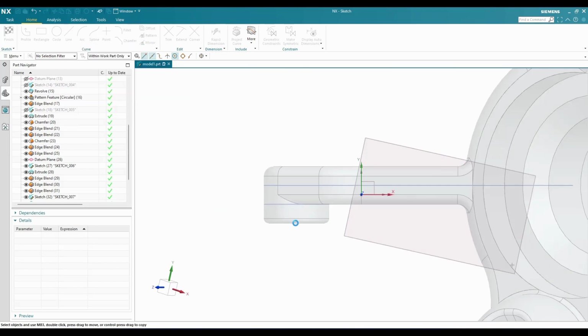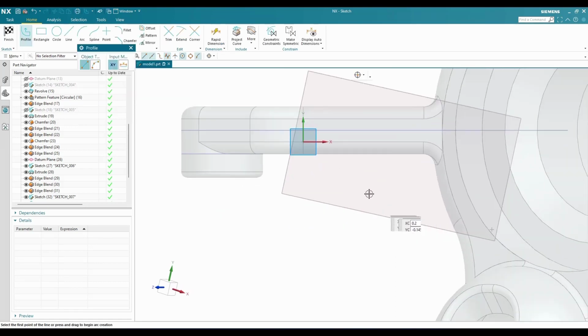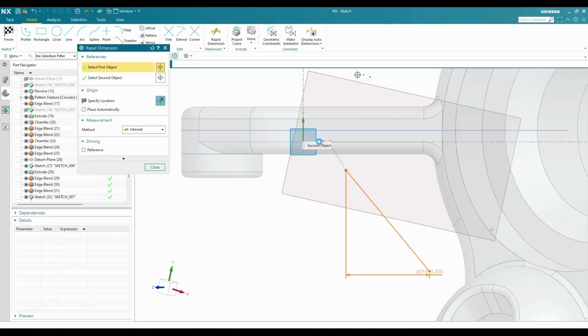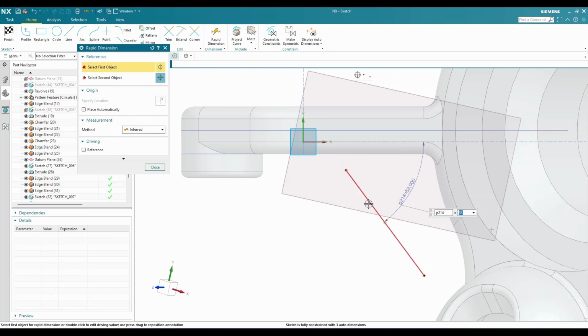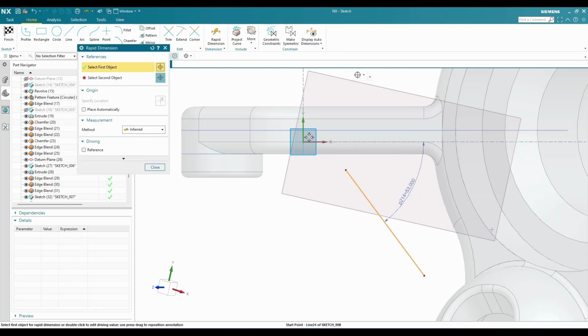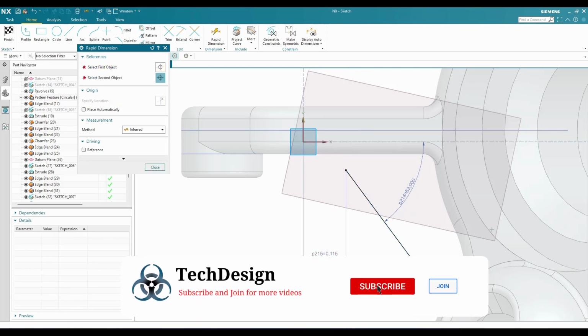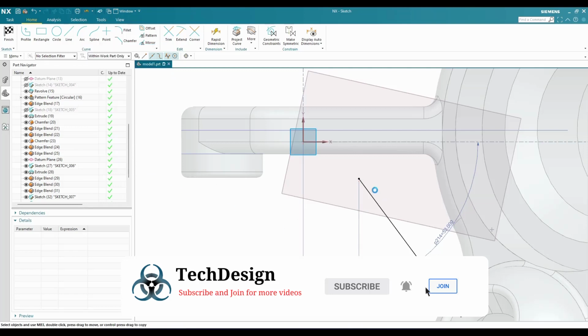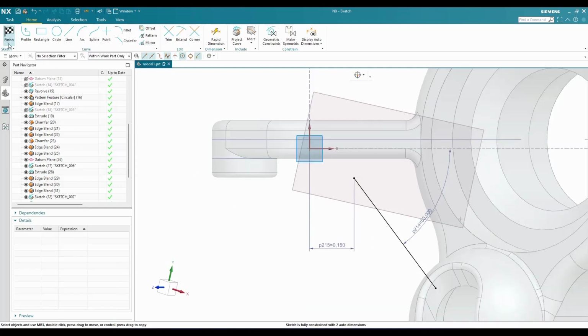You can just click OK. And here let me go to draw a line here. So this is going to be my line, and there should be an angle here between these two x-axis. So it should be 53 degree. Okay, and then there is a distance here from this point to this axis. It should be 0.15. Okay, so that's all. We don't need any other things, so we can just finish the sketch.